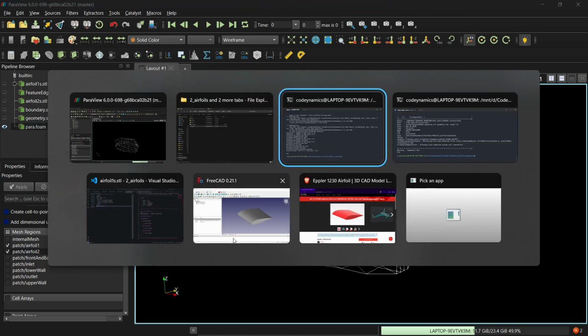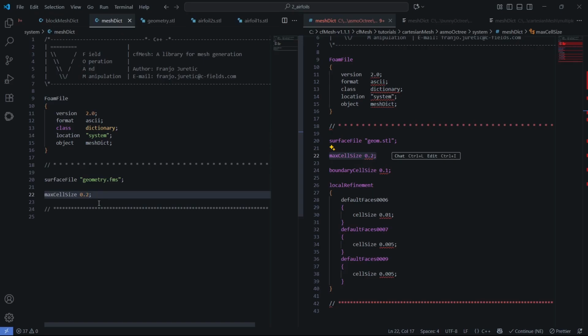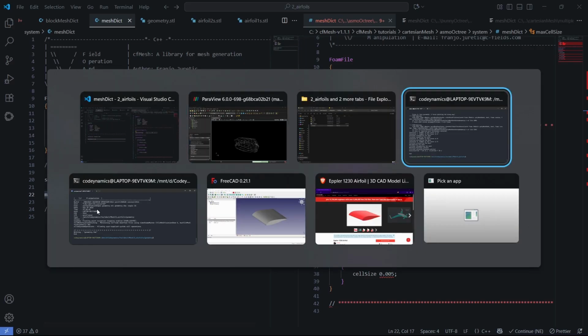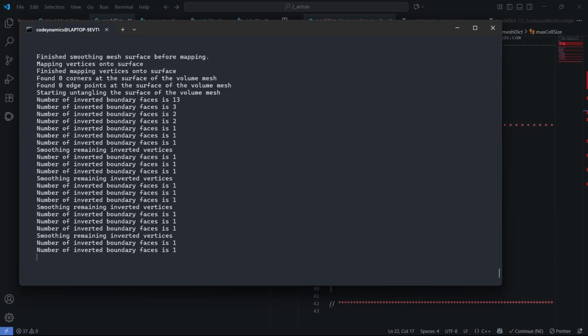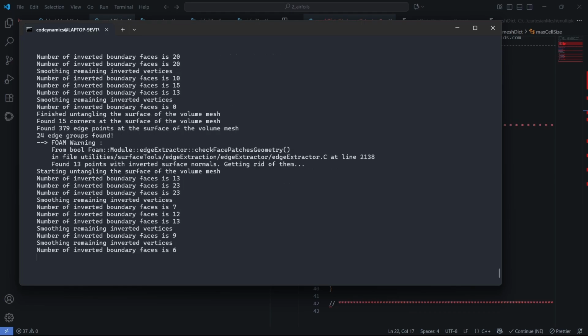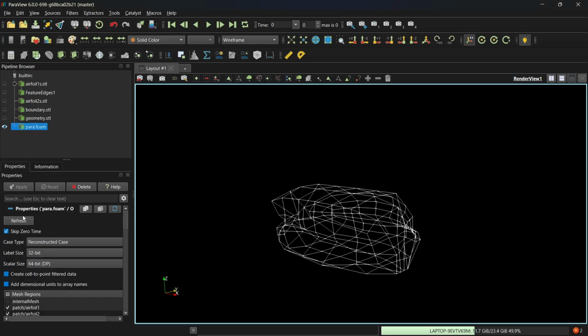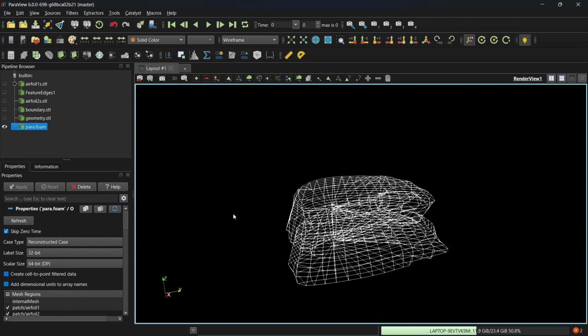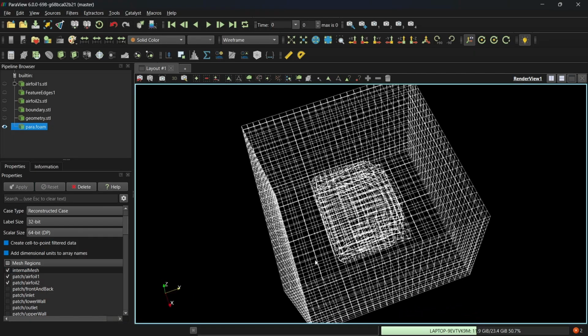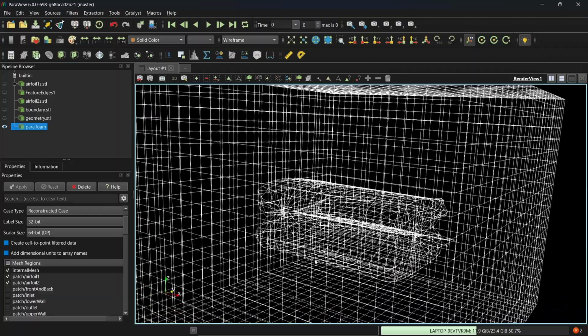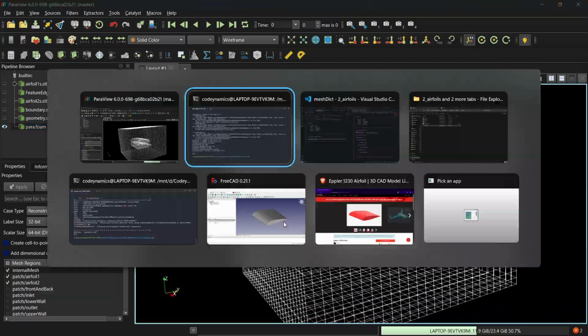Now we are going to do certain things. The first thing is go to the mesh depth, and instead of 0.2, let's choose somewhere like 0.1 or even 0.08. Okay, and let's run the mesh again. So we are choosing a smaller cell size. So now the mesh should be slightly better. Okay, the mesh also ran faster. Hit refresh. Yep, it looks even better. And if you choose internal mesh as well, yeah, the overall size looks comfortable.